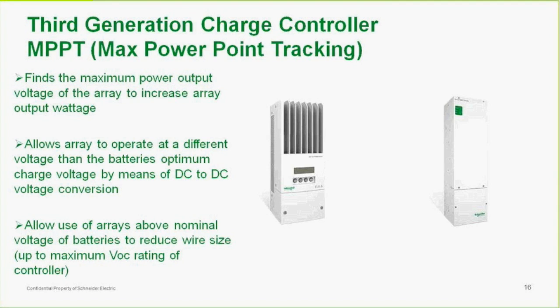Which means now, for instance, the part numbers of these two controllers we see on the right side, the one on the left is what we call the MPPT 60-150. And what those numbers mean is that it can put out 60 amps continuous DC amps, and it can have a maximum DC input voltage of 150. So we can basically operate, I guess that'd be probably a 72-volt nominal array, I believe. It depends on your climate.